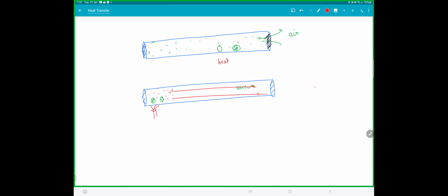So what is this? This is conduction, radiation, or convection? This is convection. This is not conduction. So heat pipe actually works based on convection. That is the reason it is so fast, meaning the molecules just rush to the right end and the whole thing becomes heated up. Whereas in a rod, you literally have to collide and move. Is that making sense, everyone? That's the concept of a heat pipe. We don't have the portion, but yeah, it looks pretty cool.